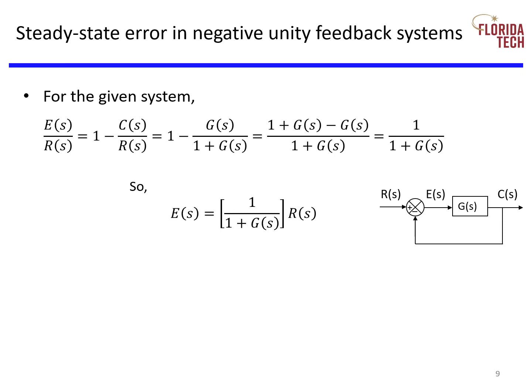For the given block diagram, which happens to be in cascade form, we know the closed-loop transfer function is G over 1 plus G. Let's substitute that into the equation. We need common denominators on the right-hand side, and when all the smoke clears, we get 1 over 1 plus G on the right-hand side.